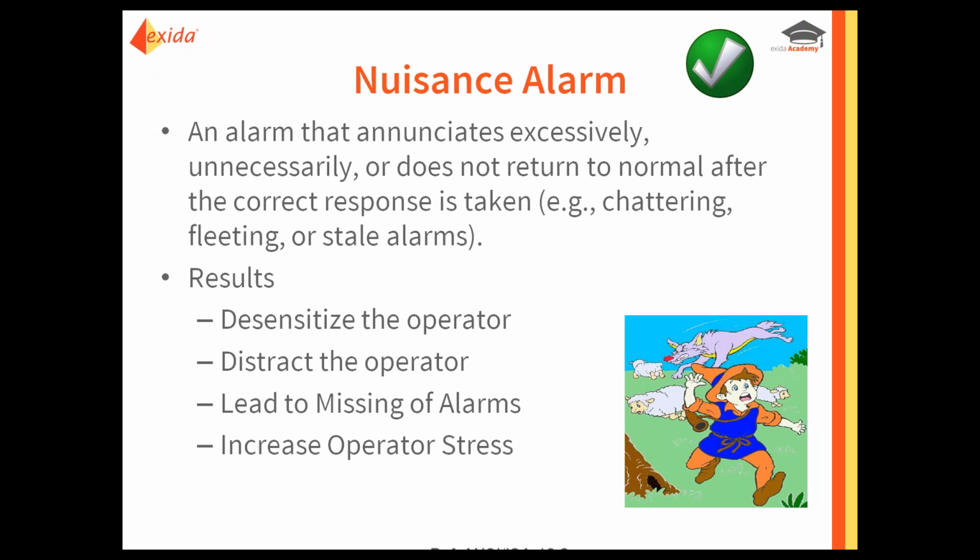So that would mean the first time an alarm occurs, the operator responds, but when the alarm doesn't clear or the situation doesn't resolve itself, that leaves them wondering about the next time. So the second and third time those alarms occur, the operator may respond or may not respond, and if nothing happens, then they are conditioned to think that it's not important to respond to that alarm or it's not necessary.